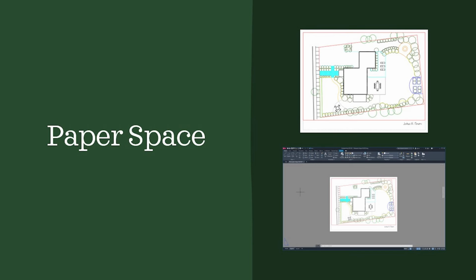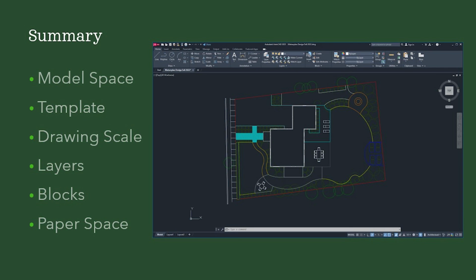Paper space was the last step of the drawing and is where the drawing is scaled to be printed. The drawing is scaled using the viewport to keep the model inside of the print margins. The drawing was first centered using the scale to fit function and then set to the scale of 1/16 of an inch equals 1 foot. After the drawing is scaled, you can add your name to the design using the text tool. This is the last step in preparing your design to be printed.